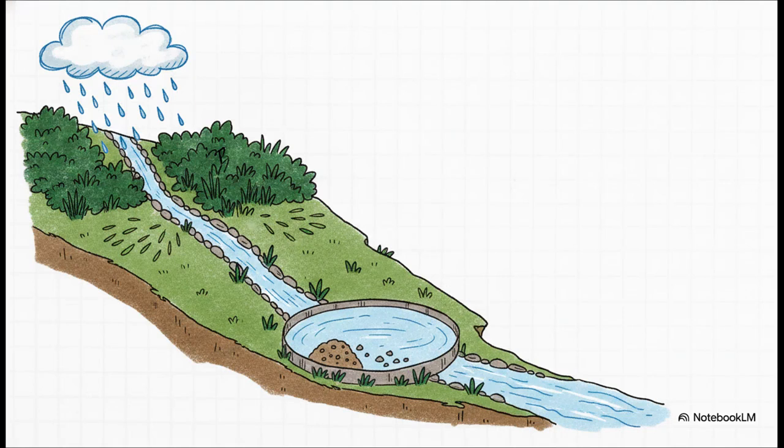And as any good detective knows, we absolutely cannot forget about the weather. Because so many nutrient problems are rain-driven and transported by storms, we have to actively manage our physical outdoor landscapes. We do this by improving drainage design, reducing bare soil exposure, maintaining incredibly dense vegetative cover, and building physical features like swales and retention ponds. We are basically building massive green obstacle courses to trap sediment before a storm can aggressively wash it downstream.